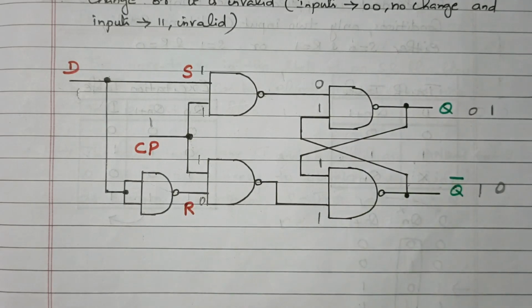So in this video we discuss the D flip-flop. Details about D flip-flop: it is constructed from SR flip-flop with the inverted input, so that we can avoid 0,0 input and 1,1 input. We discuss the logic diagram, logical symbol, truth table and excitation table. From the output we decide the input, which is called the excitation table. And we verified one set of input also. D equal to 1 means the output changes from 0 to 1.